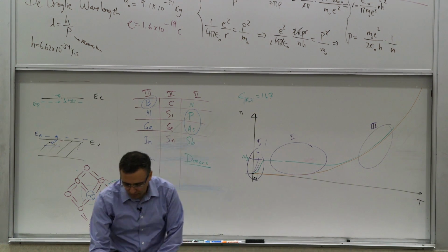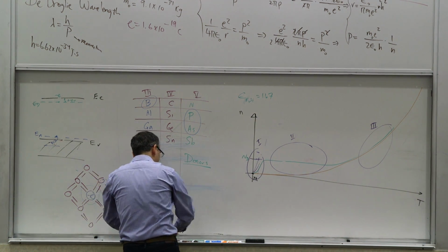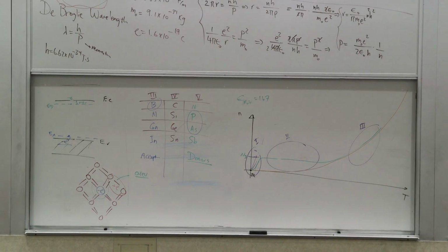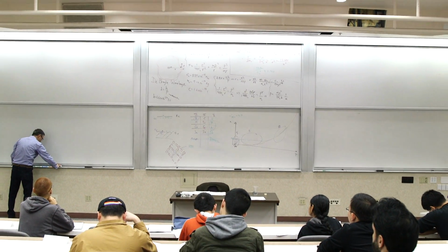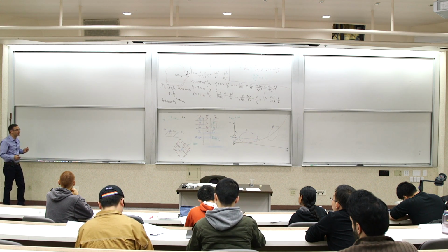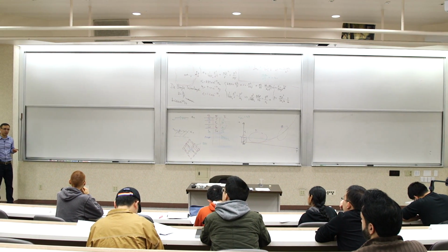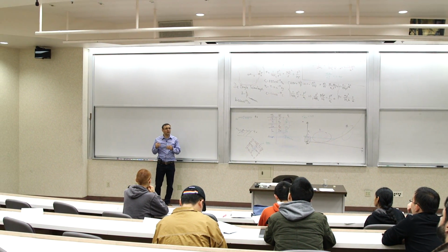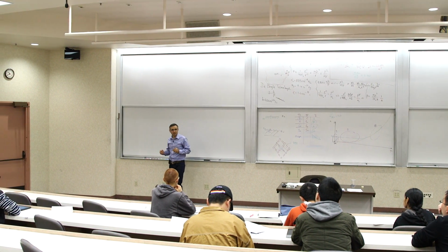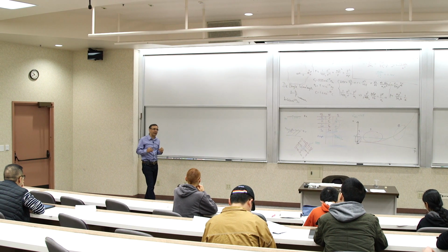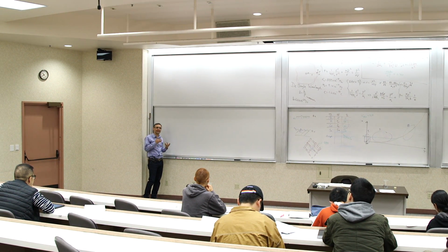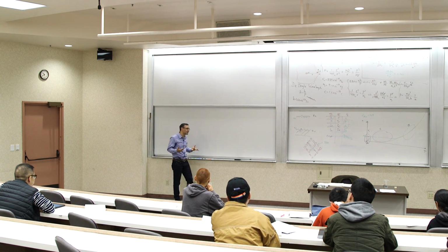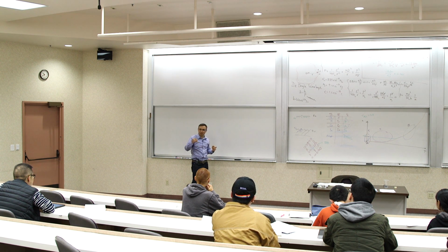Okay, so far we talked about these energy levels and all those things, but the question is, what distribution do these kind of electrons, let's say electrons, follow in a real system, particularly in thermal equilibrium? By the way, I want to clarify something, and this theme will occur again. Thermal equilibrium and steady state are not the same thing. They're two different things. And we'll see scenarios where a device is in steady state but not in thermal equilibrium. For example, when a diode or a transistor is carrying current, it's in steady state but not in thermal equilibrium.